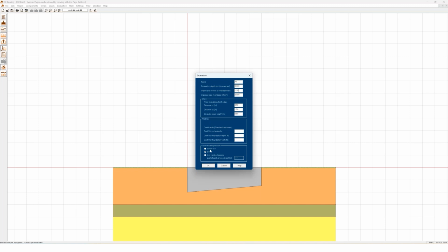And if not, and the excavation is quite deep at one side of the foundation, then we can use the active and passive earth pressure. And the earth pressure can just be as high as much as the load can activate. So it won't happen that the passive earth pressure would press the foundation against the load side.